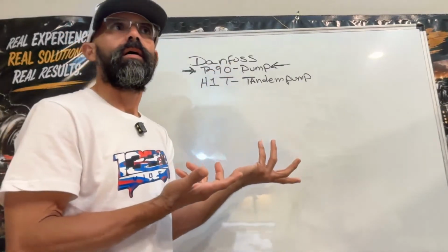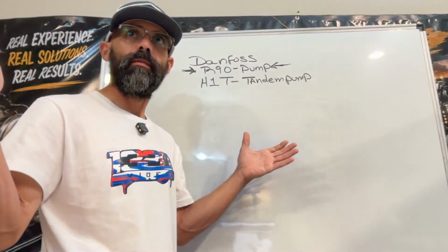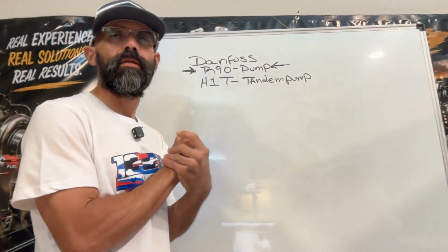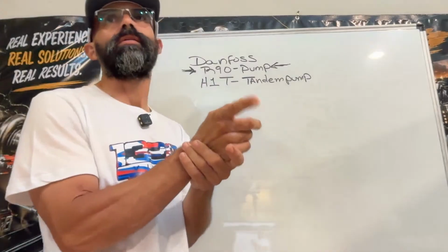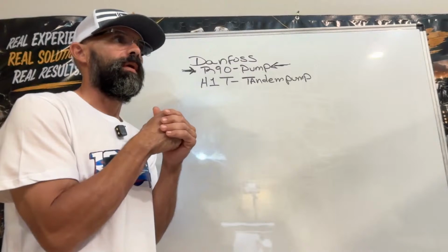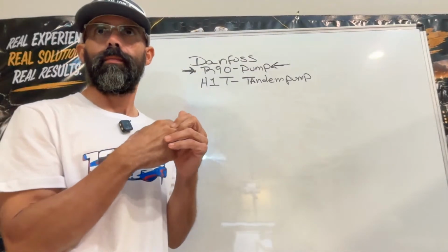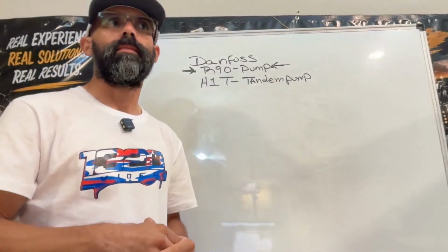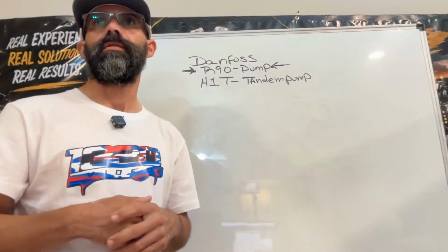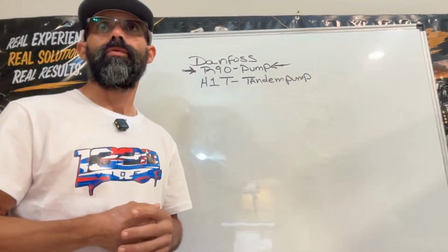So if you have, let's say, an 80 by 100 or 100 by 120, you're going to have three pumps that look the same. The closest one, attached to your bell housing at the back of the engine, is your rotation, clockwise and counterclockwise. The middle one is your thrust and pullback. And the last one is your mud pump. You have a bigger mud pump, that's why it needs a high flow and a bigger hydraulic pump in the system. But each individual one has its own charge pressure relief valve, right?